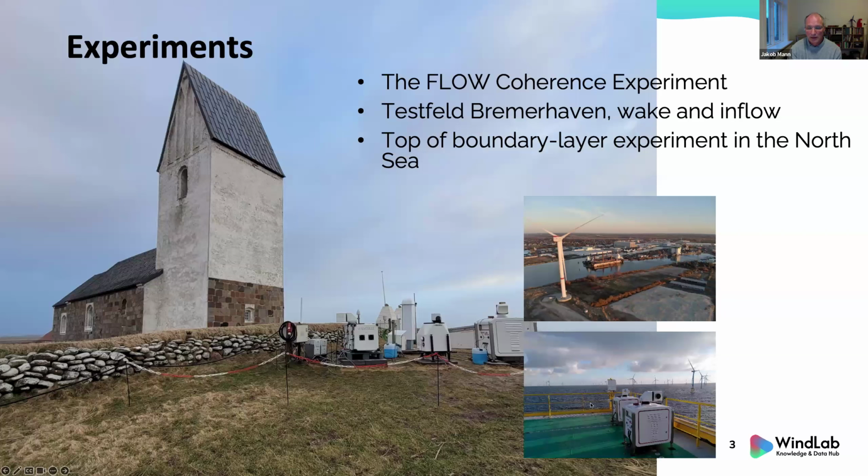And lastly, we have an experiment which is a continuation of an already existing experiment in the North Sea, where we look specifically at the boundary layer top, because the large turbines of today and tomorrow will penetrate the inversion, or can sometimes penetrate the inversion. We thought it could be interesting to see what kind of velocity differences we see over that inversion and how they would potentially affect loads and also energy production. So that's some of the experiments we have.